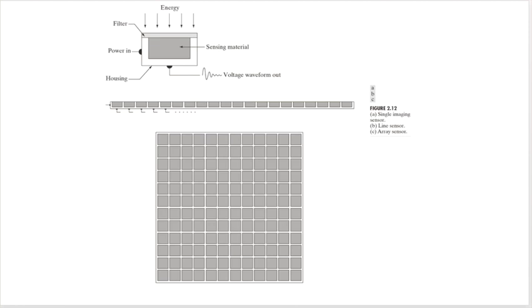If I took two semiconducting materials of the same stuff and stuck them next to each other, what happens? It becomes one. So if you don't have those gaps, you don't have a bunch of pixels, you've got one big pixel. And it's just going to take everything across the whole thing and average it, right? Because no matter how much high resolution comes in, you're going to have an analog image coming in. If you have really big sensors, it's just going to average. If there's some grayscale in there, it's going to find the mid value, and that's it. You lose all detail. That's why you get this kind of chunky box look.